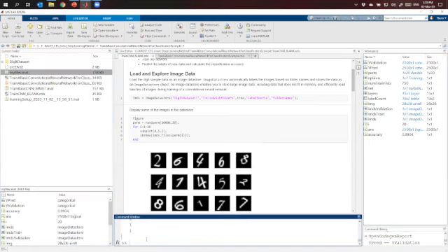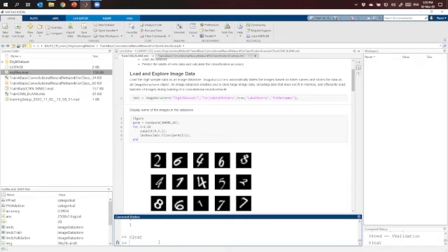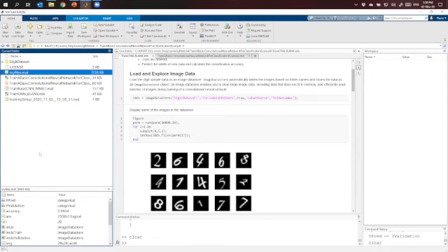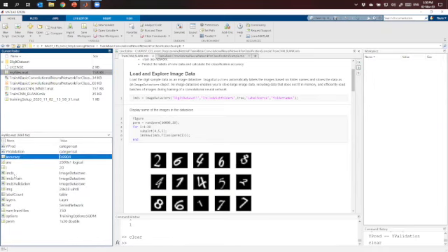And now let's clear what we have. If I write clear and press enter, I'm in the command window down here. Okay? It's going to clean everything in my workspace. So my data is gone. But if I want to bring it back, I saved it. So it's here. What I can do is bring separate values. So let's bring only my neural network.